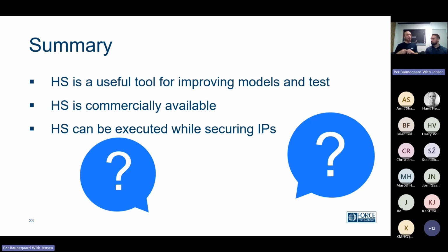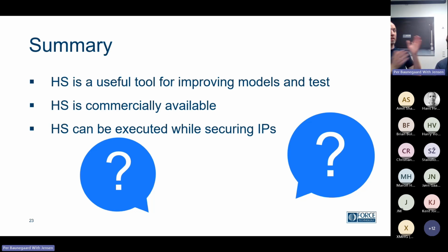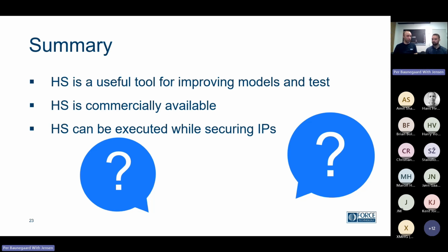But then what could be really interesting, because we also know that the jackets redistribute the forces. So the force is low at this one joint, but then at another joint, it increases. So you could then have two or three tests running simultaneously. As it goes down on this one, it goes up on this one. How does that affect the lifetime of that joint? So hybrid simulation also allows us to have multiple tests running that can influence each other via this model. Exactly.